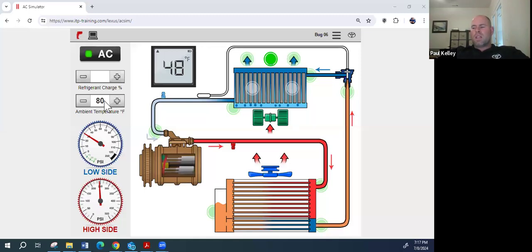So if you weren't exactly sure how cold it could blow, let me help you understand. In service information, it doesn't give you a number. TIS will not give you a number like 48 is good because that number depends on your ambient temperature, it depends on your humidity. You could probably find a chart somewhere, but even that is not specific to this 2013 RAV4. So let's make it a 2023 RAV4 because these are getting old, but they're still amazing. Let's just say it was a 2023 RAV4 and it was blowing 48. What could you do to tell if that RAV4 had a problem or not?